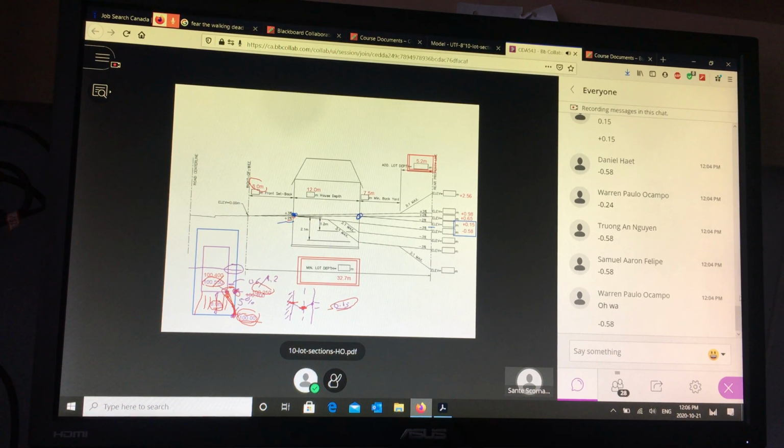One of them is going to work, and you're going to end up with a split point somewhere between the front and back of the building. The split point has to be between the front and the back of the building if you're in a split draining situation. Front drainer is the exception, obviously. So if you're between positive 0.15 and negative 0.58, you're going to have a simple split where the split point is either at the front, at the back, or somewhere in between the building.